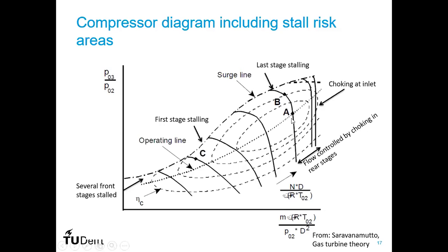So you have a constant reduced mass flow rate at the same pressure ratio, so the pressure ratio does not determine the mass flow rate anymore. At the low pressure ratio it still determines it, but at this one it won't. This is sometimes called in compressor theory the stone wall, because you don't get any more flow through it.